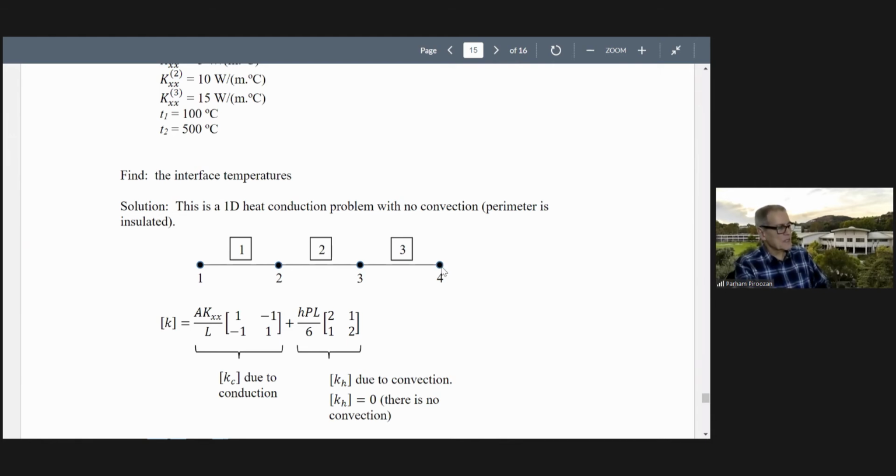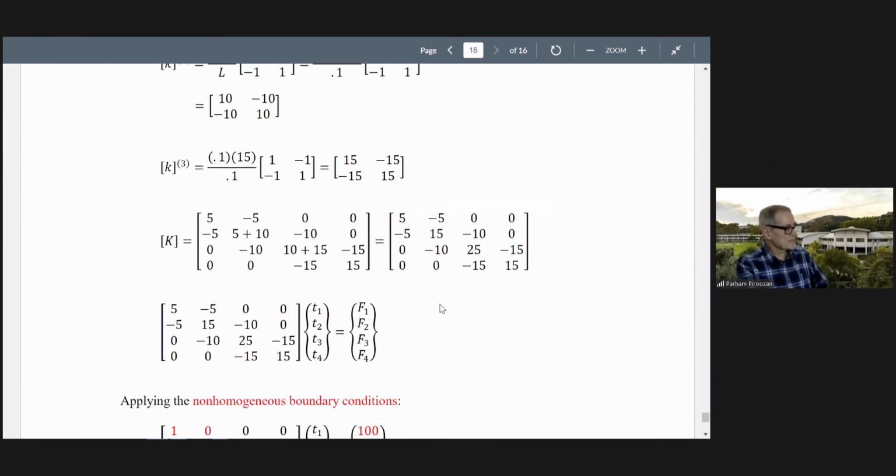It doesn't have an X direction or a Y direction, like the displacements we had, for example, in solid mechanics for two-dimensional problems, of course. But temperature is just temperature, one scalar at one point, one unknown. So 4 nodes and 1 degree of freedom per node. So our global stiffness matrix should be 4 by 4. That's it.